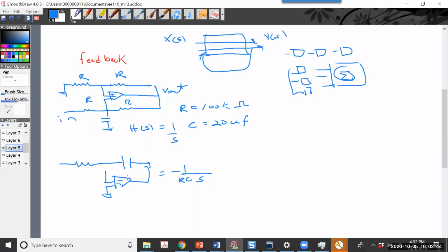And what's going to happen is we're actually going to use this one and we just keep track of the minus sign, right? They're always using a non-inverting integrator, right? But this takes more parts than this. This is a lot simpler to use. So this is the structure for the kinds of filters that we're going to be using.